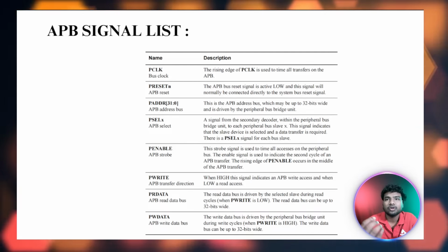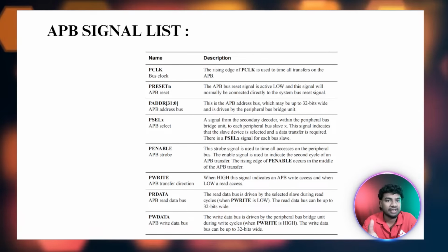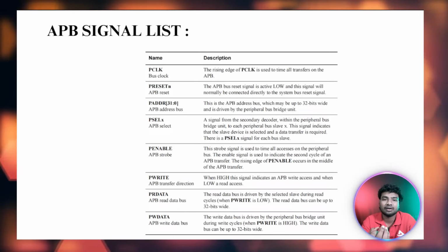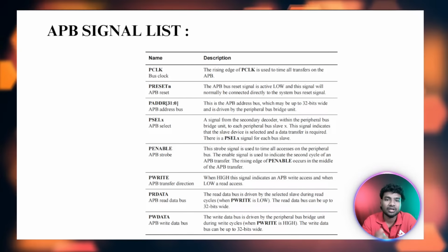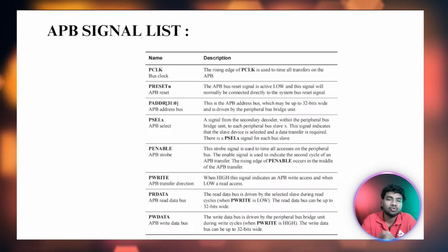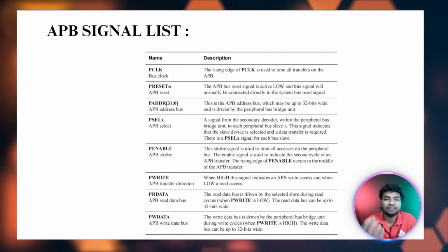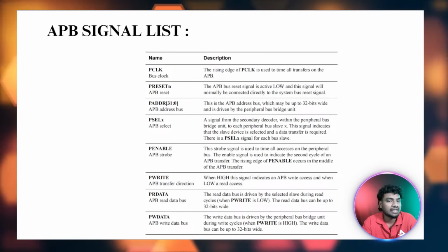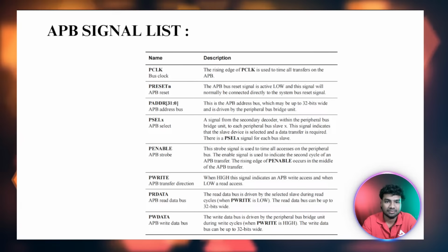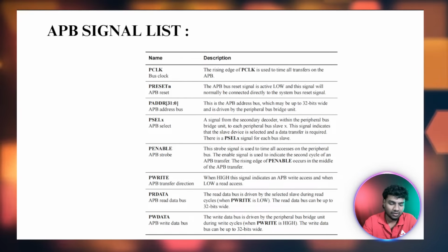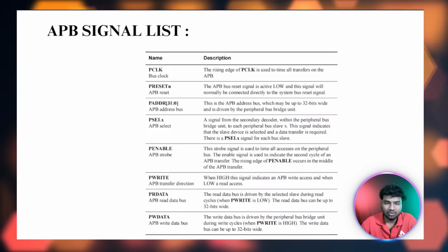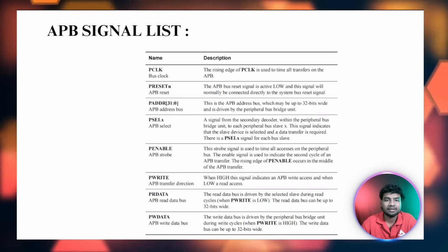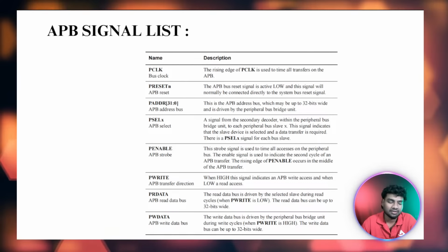If you are using 5 slave devices, you need at least a 3-bit vector to define the 5. If you are using 10 slaves, you need 4 bits. So based on the slave count we can increase the slave address width. We can assign as many bits as we want for the slave address vector.